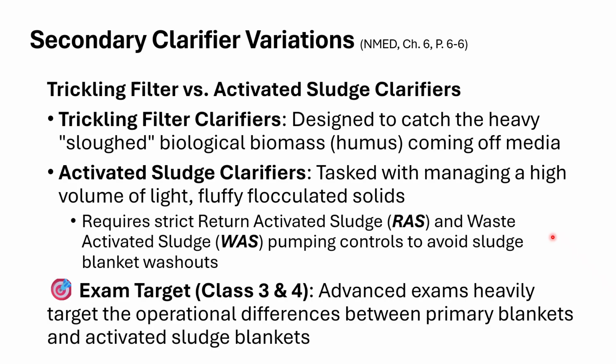Okay, so we want to size the sludge pump at such a rate or such a size that we can easily deal with that sludge blanket without worrying about overflowing or accreting a very large sludge blanket by the amount of waste coming in or sludge being produced in the secondary clarifier.